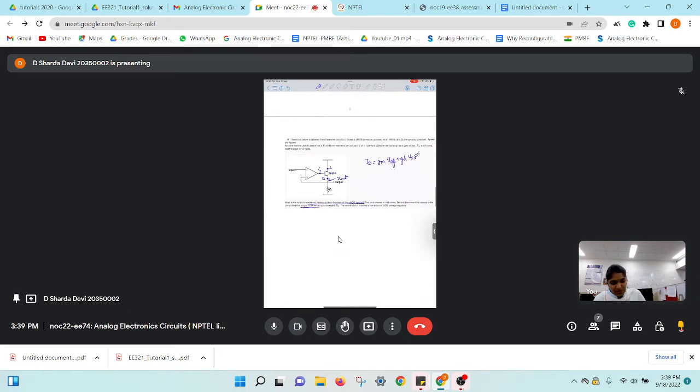So the expression that you'll get for Z out in case of PMOS and interchanged terminals will basically be r naught upon 1 plus gm r naught A. And this value is very close, again 18.42 milliohms. But when you look into the expression, that plus 1 which was there earlier won't be here in this case. That is because source and drain have been interchanged. Easy, no?